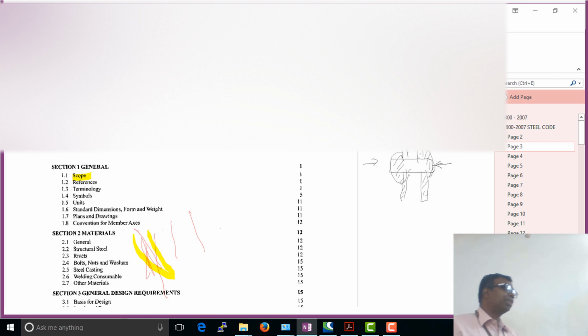Okay, so now what's happening here is this is outdated because this requires a lot of equipment, and the other thing about rivets is you can't remove them very easily. You'll really be damaging it because it's almost like a permanent connection which you get in a rivet. But today we are having what is known as the high yield strength friction grip bolts.